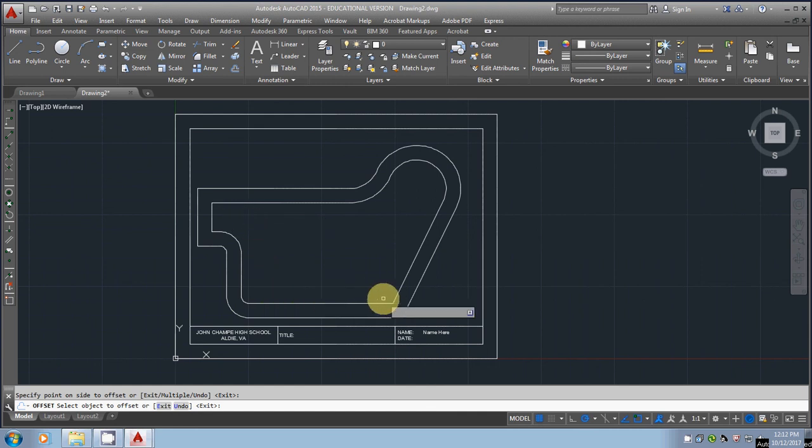The last step that we want to do is do a final fillet. So choose that. I'm going to change the radius a 4th time to 0.5. And I'm going to fillet this little corner down here to round that over. So once you have that, you just need to title it and call it the Gasket Design, add a date, and save it.